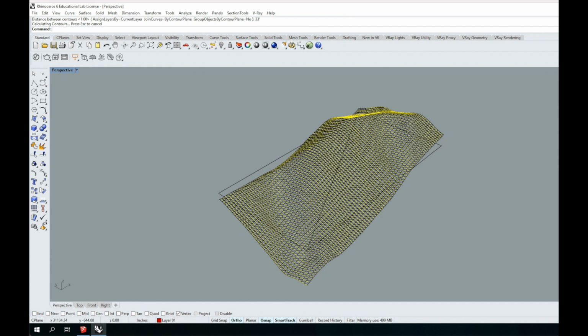So I have all of those curves. I could rename layer 0 here to be contour X for clarity. So let me type contour X there. And then let's change layer 2 here to be contour Y.